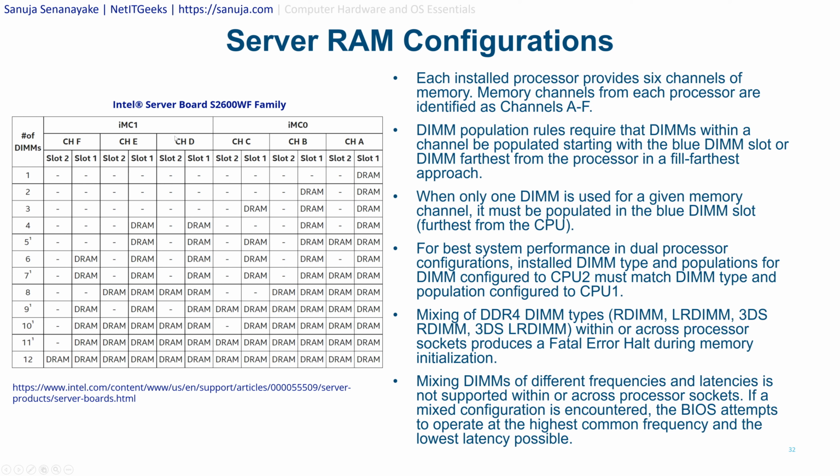So the manual will give you a table like this, and it will tell you how you can populate a limited number of RAMs. If you have all the RAM sticks available to populate every single DIMM slot, you can just populate everything. It's no problem on the slots. But if not, you have to follow a table like this. In this particular Intel server board, they also give you some bullet point instructions. I copied directly from the manual for this particular server board, posted on this website.